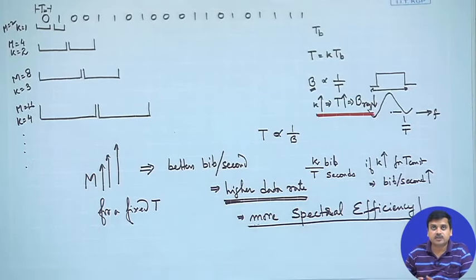Now, as communication engineers, we should be updated with the latest requirement in terms of wireless communication systems: the more bits you can send per second for a given communication system, the better it is. For example, if you are given 1 megahertz of bandwidth, and you are choosing 1 bit per symbol duration, compared to another system which chooses, let us say, 6 bits per symbol duration, the second system is actually transmitting 6 times higher bits per second compared to the first system. So, the question that could come to our mind is, does it come for free?